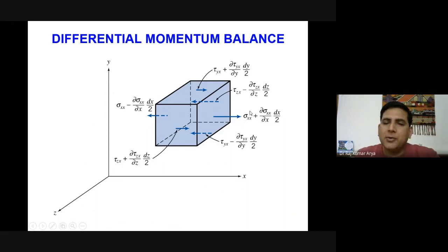Therefore, normal stresses are defined by sigma. Wherever direction and plane are the same, you can change that tau into sigma, and that is known as normal stress. Wherever they are different, let's say tau yx or tau xy, they are treated as shear stresses. Is that fine? Shear is always parallel to the surface, and normal stress is always perpendicular, either outward or inward. Fine.